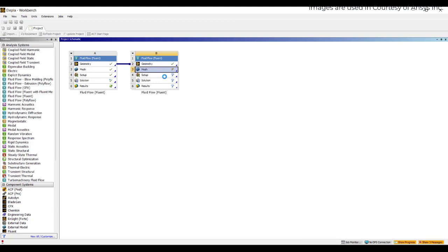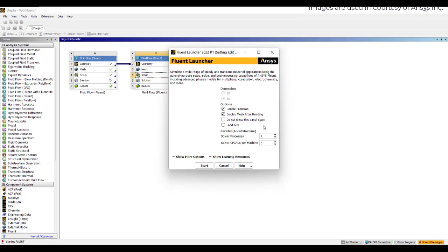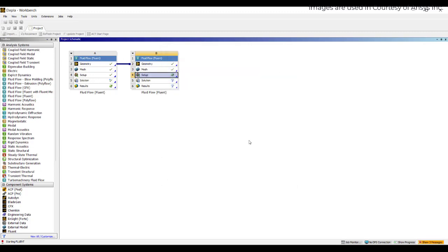Here we are concerned about the cathode plate onto which the chromium ions will be deposited, or the chromium metal will be deposited according to the shape of the cathode. Depending on the shape of the cathode and the anode, the amount being deposited will vary. So you need to take that variation of shape into consideration as well, because the deposition content will change.